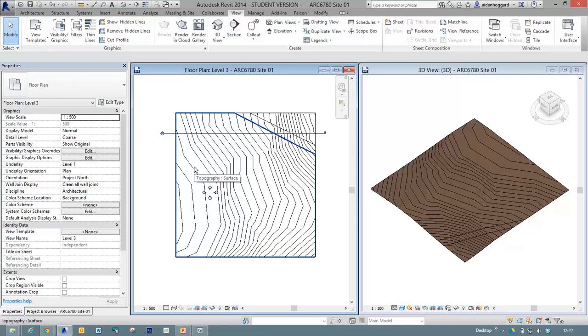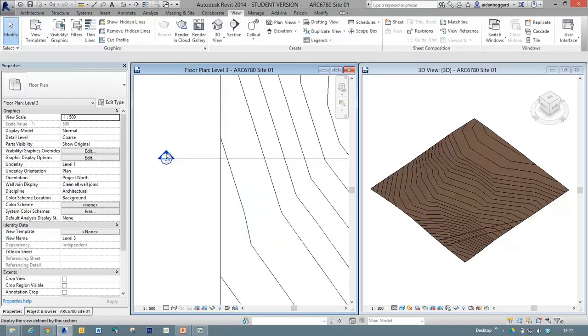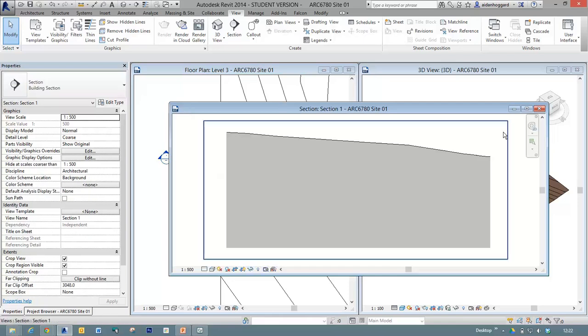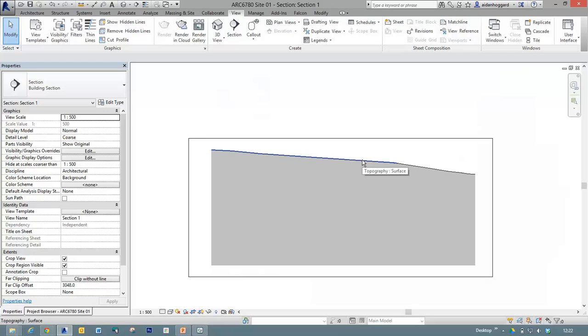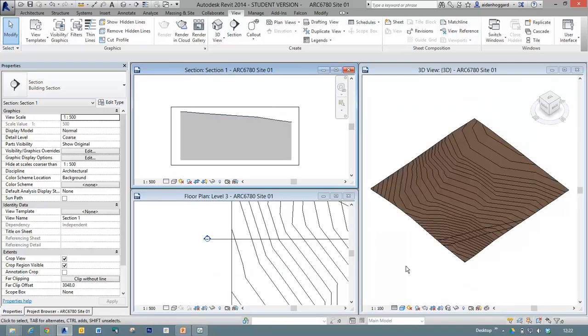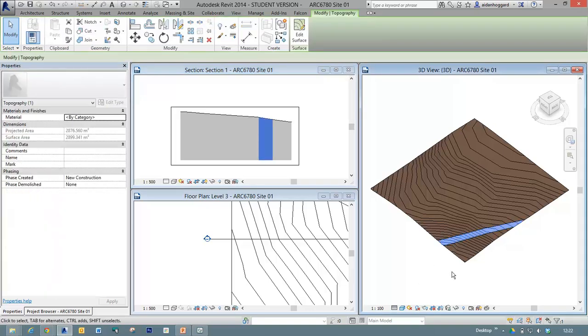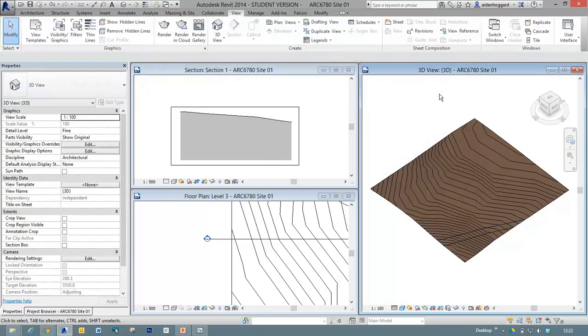And this is where you start to see the real benefits of working in a 3D environment, particularly when you have buildings modelled. If we now just double click on that section line, it takes us into our section through that site. Because it's a 3D model, this is not a 2D drawing of a section, it's live, three-dimensional information. WT, Windows Tile, and I'm just going to select that road surface.